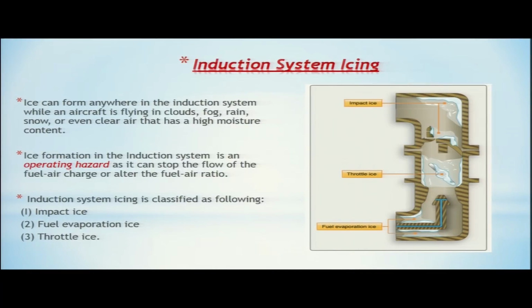Ice formation in the induction system is an operating hazard as it can stop the flow of fuel air charge or alter the fuel air ratio. Certainly it is an operating hazard. You can see here in the diagram, this is your throttle, this is the carburetor, and you can see ice being formed at various places. When ice is formed at various places, it can stop the flow of fuel air charge or it can also alter the fuel air ratio.